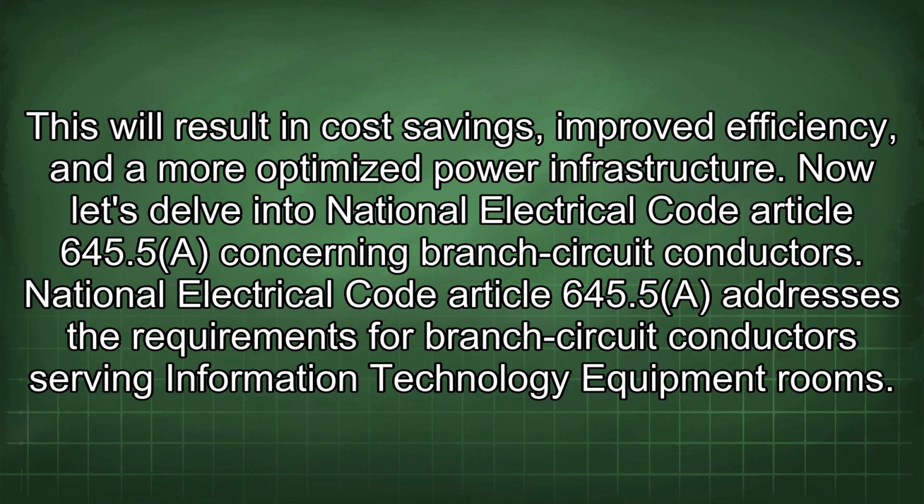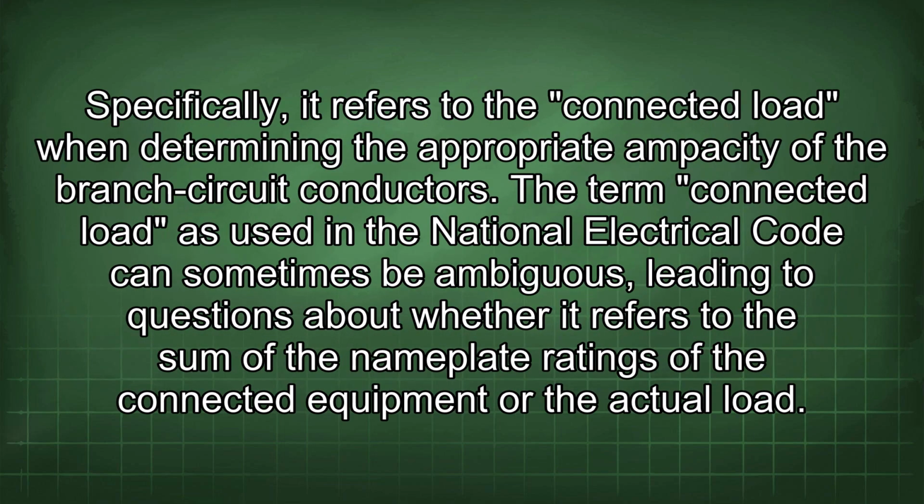Now let's delve into National Electrical Code Article 645.5 concerning branch circuit conductors. National Electrical Code Article 645.5 addresses the requirements for branch circuit conductors serving information technology equipment rooms. Specifically, it refers to the connected load when determining the appropriate ampacity of the branch circuit conductors.